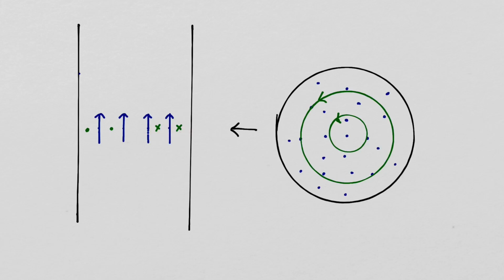Let's look at what happens if you try to now increase this current. If the current starts to increase, we know the magnetic field intensity will start to increase. This changing magnetic field intensity will generate induced currents, and we know from Lenz's law these induced currents will be in a direction to produce a magnetic field opposing the increase in the magnetic field from the increase in the current down the wire.